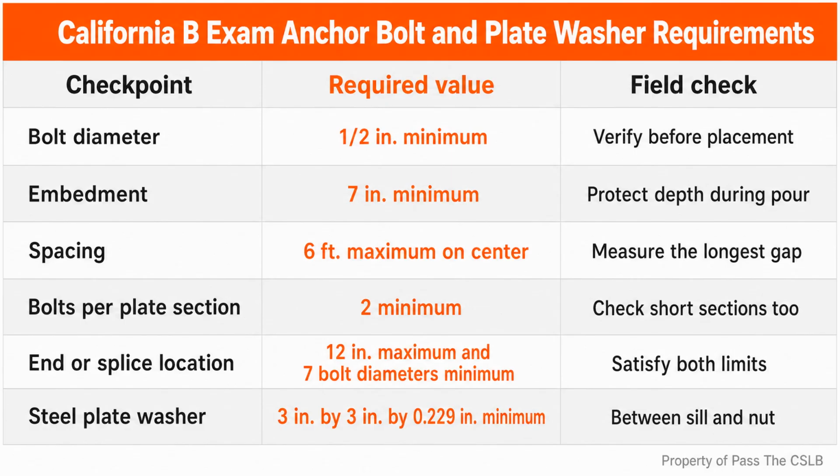Concrete hardens through hydration, a chemical reaction that begins when water contacts cement. As time and mixing continue, the mixture loses slump and becomes harder to place. The dangerous shortcut is to treat an old, stiff load as a workability problem that can always be solved by adding water. Uncontrolled water changes the water-to-cement relationship and can reduce strength and durability.